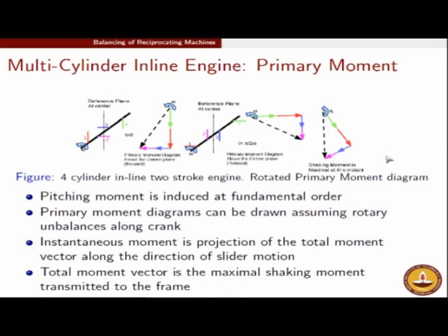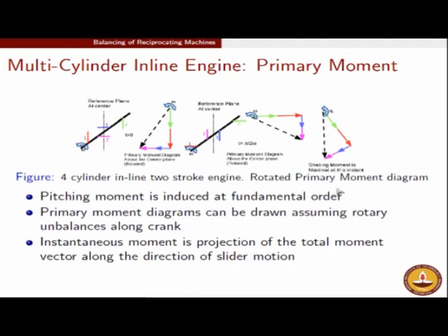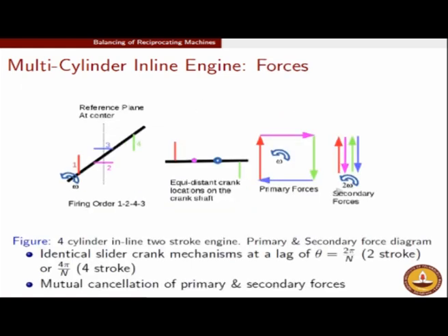And I think at this stage I will conclude my talk here. I will be available in the next 2 odd minutes that are remaining, and even afterwards if you wish you can interact with me. The last part had been a little fast to my satisfaction, but I hope you get the idea that the build up from the rotating unbalance is very important to understand the reciprocating unbalance, and it is very important to appreciate the role of approximate models in our understanding of how unbalanced forces can be mitigated, how in a multi-cylinder inline arrangement the unbalanced forces are actually getting nullified, and how there are moments that are left in the multi-cylinder configuration that are induced in the crankcase.